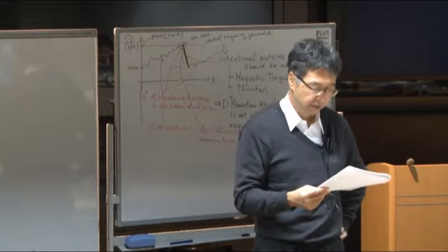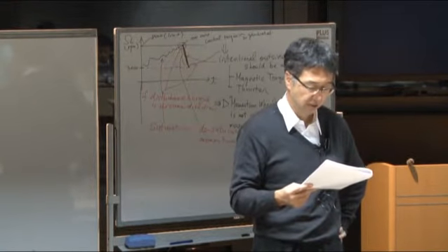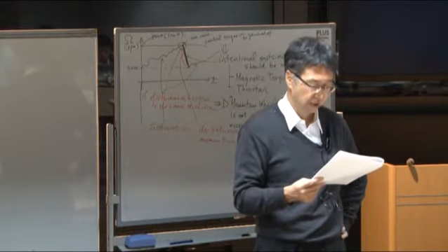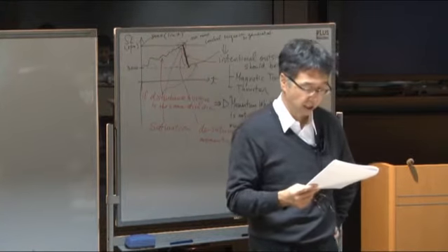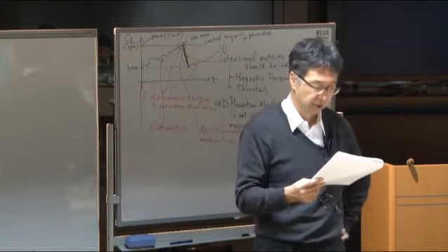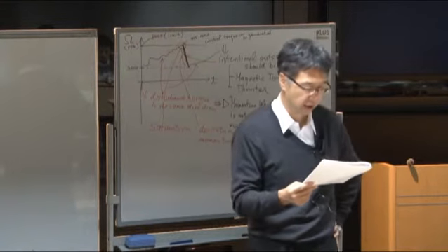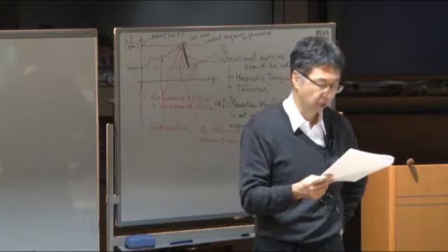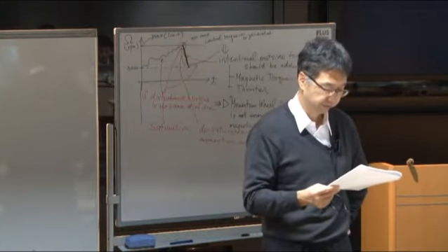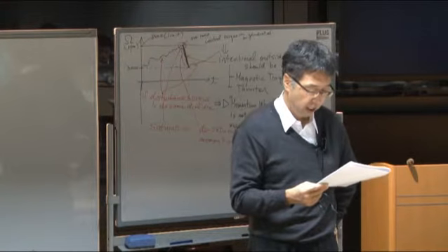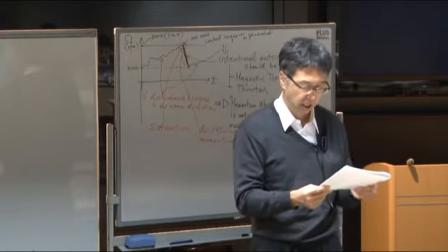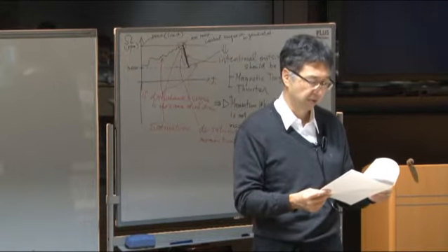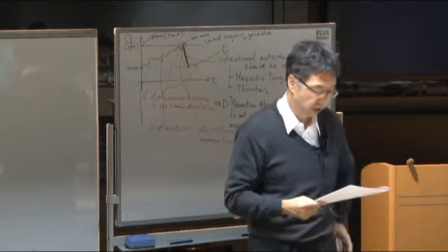Okay, and number seven is axis definition. In the orbital frame, the yaw axis is directed toward the center of the Earth, the pitch axis, that is the y-axis, is perpendicular to the orbital plane, and the x-axis is usually toward the velocity vector direction. And the eighth one is just a formulation of the schematics of the dual spin satellite. So, let's go to the next page.